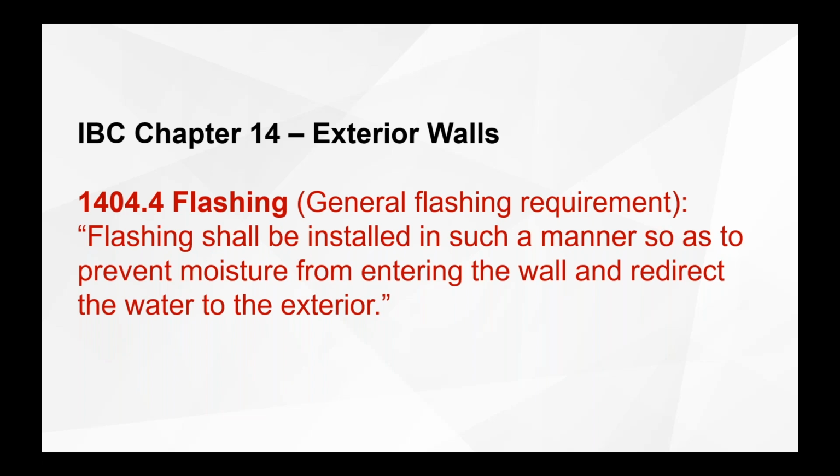So the lawyer started asking me real simple questions like, what's a stucco accessory? And then they started asking me all these easy questions. And then they circled back and said, okay, so the water was coming through the windowsill. Now that was well documented. Everybody knew that. I said, yes, the water was coming through the windowsill. And he said, okay, and what was that stucco accessory that you used at the window? I said, I used a short flange casing bead on that. He goes, tell me, why didn't the casing bead redirect the water to the exterior?